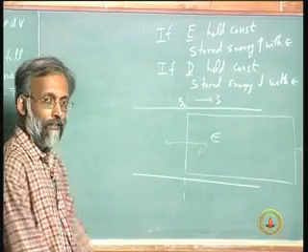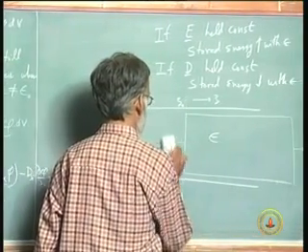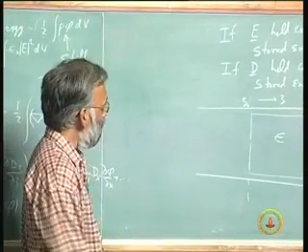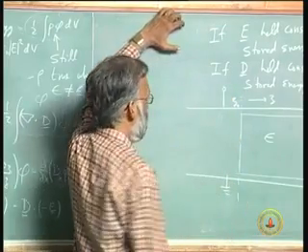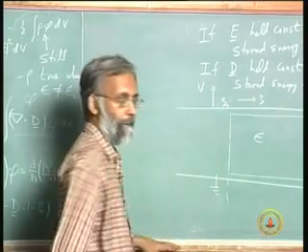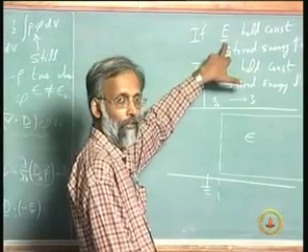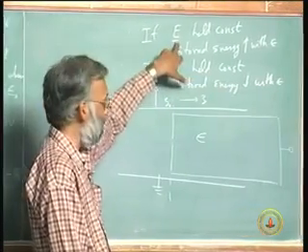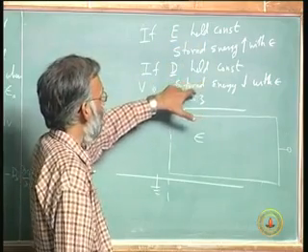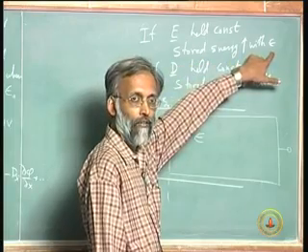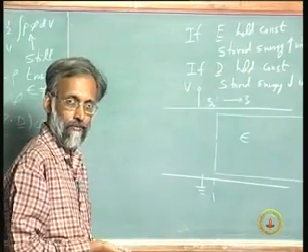Now, the way to do that is first of all to understand why there should be a force and then to calculate it. Let us look at that problem. Now, supposing I held my capacitor to some voltage V. Now, I know that if I hold the voltage to some constant, then effectively I am pinning down E, because integral E dl is the voltage. So, I am essentially holding E constant. Now, if I hold E constant, I find stored energy increases with epsilon, which means that by pulling this in, I am going to increase my stored energy.